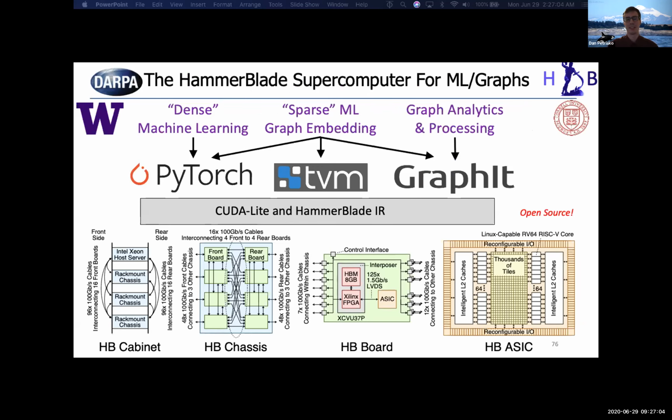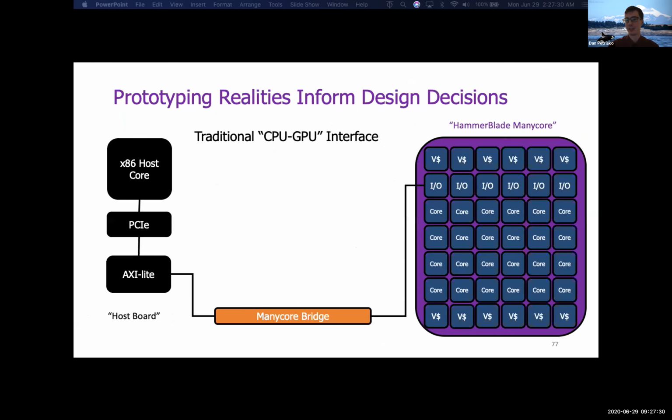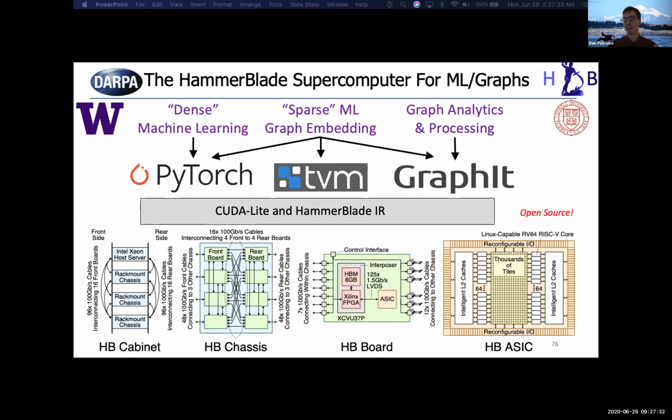In the past, you can look up Celerity, which was the previous version of Hammerblade, and it had one layer of these RISC-V cores, these very tiny area optimized 32-bit cores, and then it had a large array for neural net processing or graph processing, more to the point. So the infrastructure itself is designed so that the tiles can be tailored to whatever you need, even possibly using FPGAs within the mesh to reconfigure what you need.